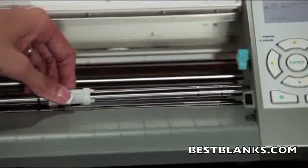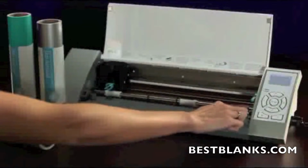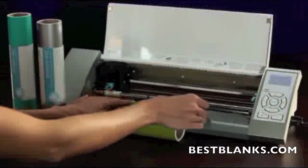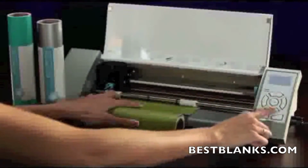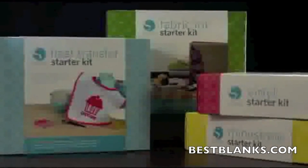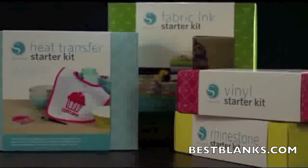Adjust the pinch rollers to fit your media on the Cameo by unlocking the main roller shaft and twisting the right hand roller. Special notches mark where the A4, letter, 12-inch, and 13-inch sizes are. Lock the shaft back in place and load your media by choosing Load Media on the Cameo LCD screen and pressing Enter.